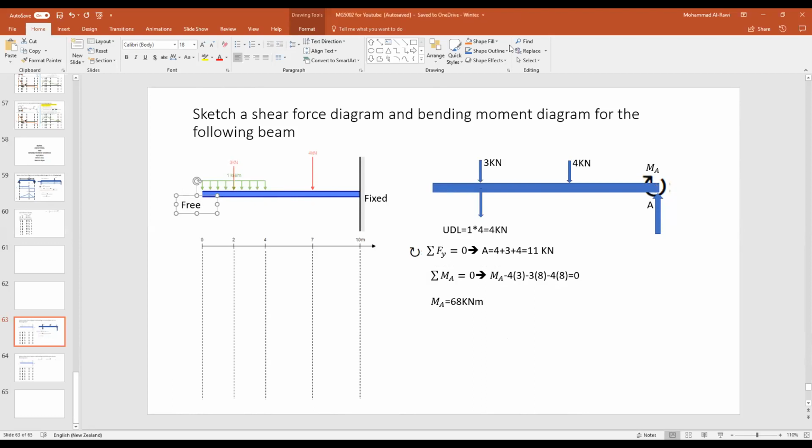There was another question I see from the chat. It's saying, how about the horizontal force in this example? No, if you see, there is no horizontal force in this example. Therefore, the wall at this stage is not providing any support in the horizontal direction. It's only providing vertical and moment. But if there was a force in the horizontal direction, yes, I should have a force opposite to that, equal in magnitude. So that's why I'm not putting a force in the horizontal direction.